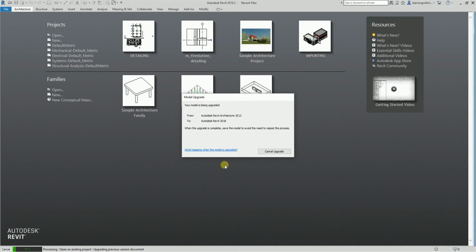All right. And one thing that you need to consider when using a drafting view, similar to other views like floor plan, section, elevation, is that drafting views are listed in the project browser under Drafting Views. So you will be able to see later on that once we create the drafting view, it will be listed in our project browser. Another thing is, all of the detailing tools that we use in detail views are available to you in drafting views. Okay, so you can add 2D drawings on your drafting view using those detailing tools.